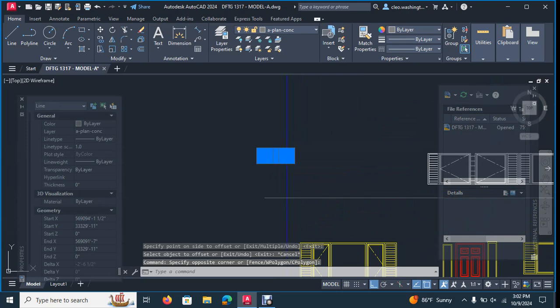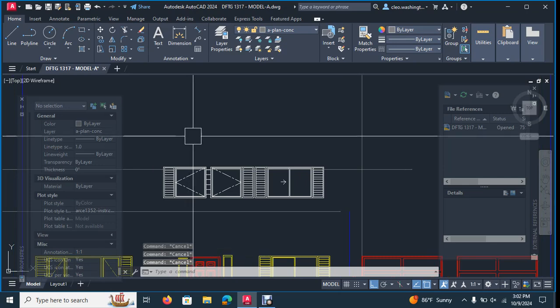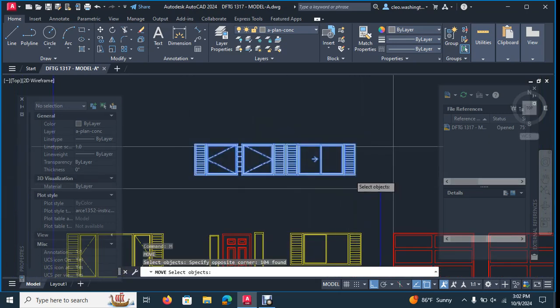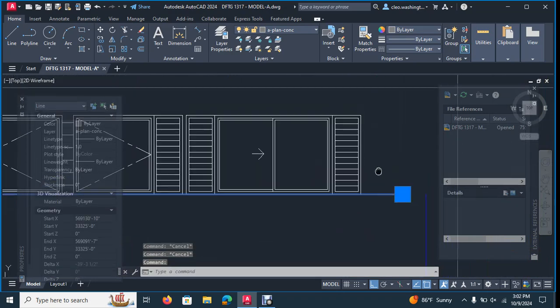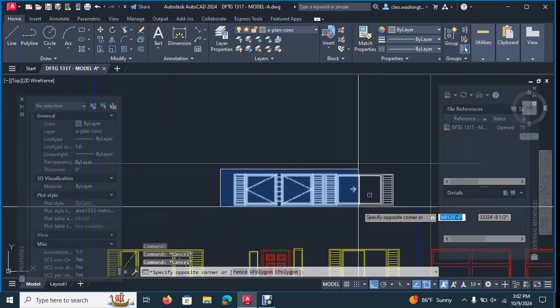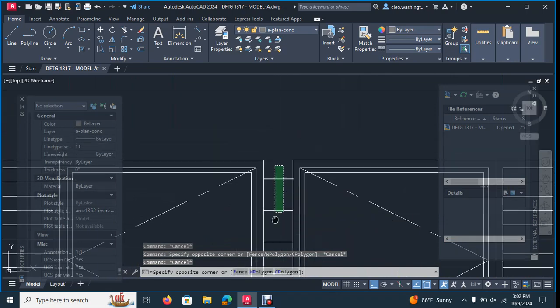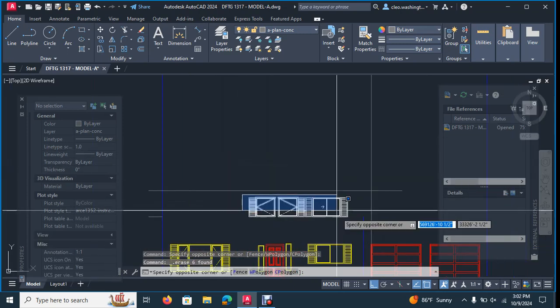Alright, so this is the bottom of the fascia plate right here. So what we have to do is move these windows down. Let's go ahead and delete this line. And now what we want to do is place them on the windows. Delete this hatch right here. Delete. Let's go ahead and put them on the windows layer.